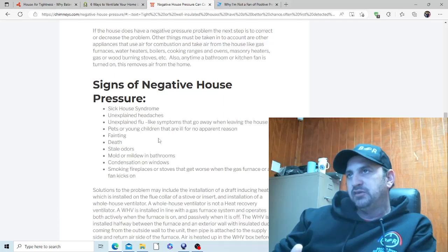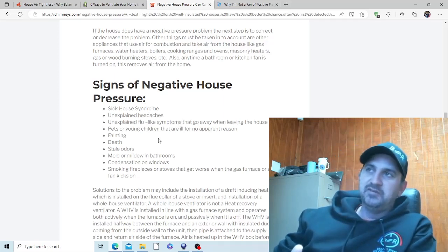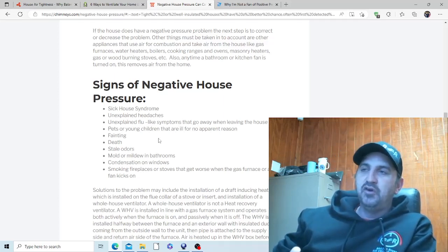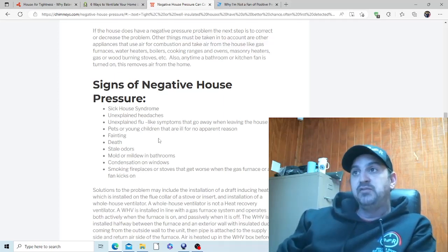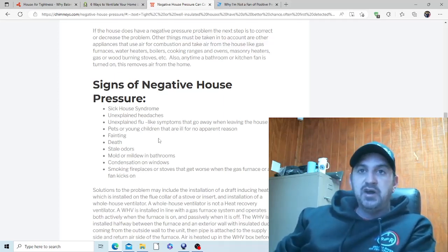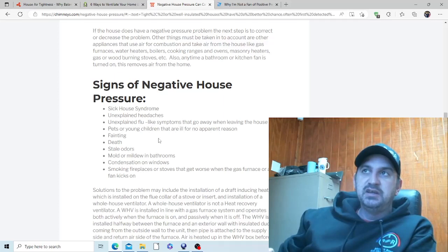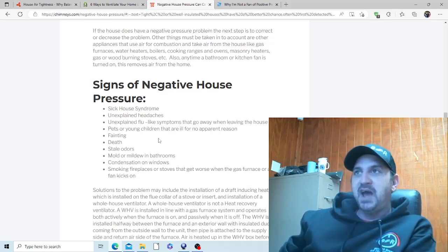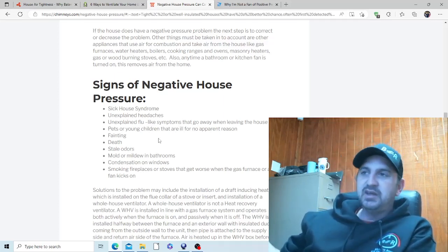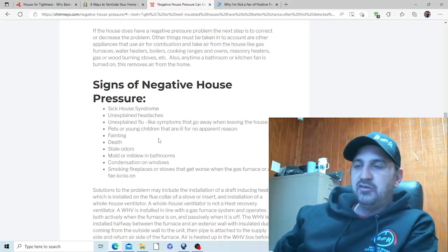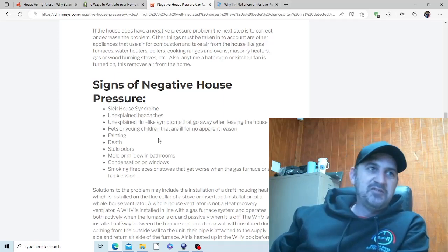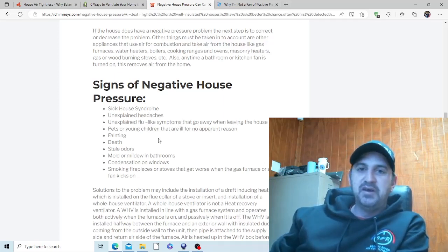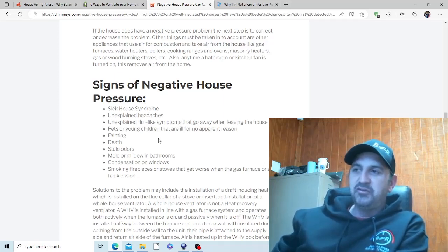And so basically, this type of home produces a whole lot of problems when you see condensation on your windows. You'll actually see this a lot on spray foam homes. If your house is built with no fresh air intake and you're not adding any pressure to the house, you're just taking it out of the house, or your unit's mis-sized or whatever, it ends up condensating the inside of the windows a lot because air can't pass through anywhere.